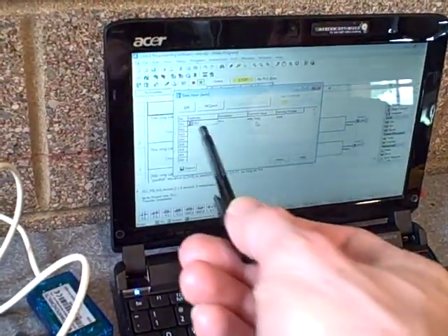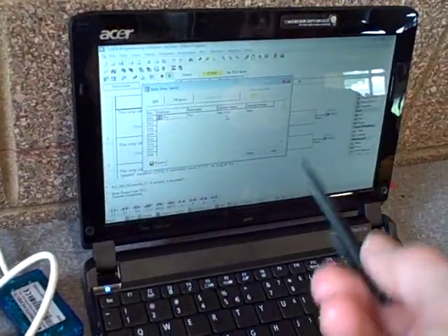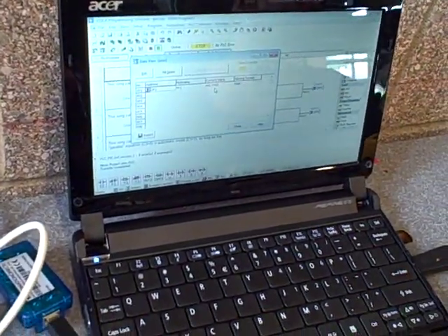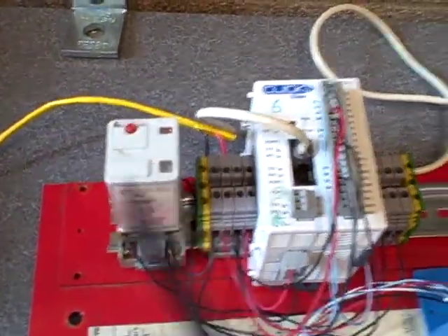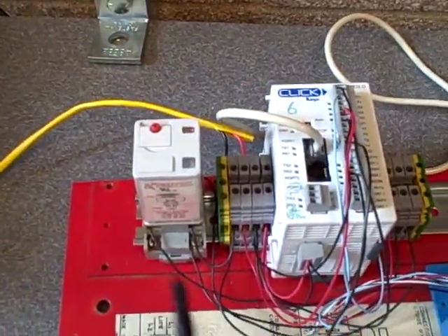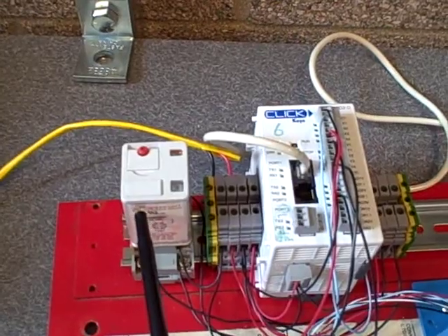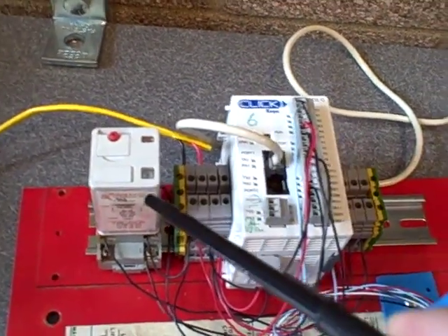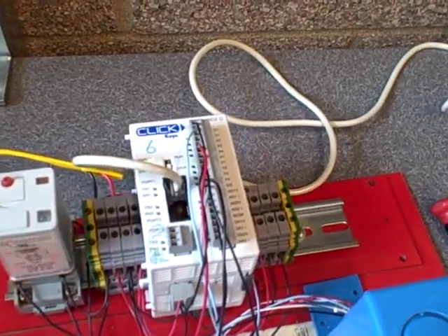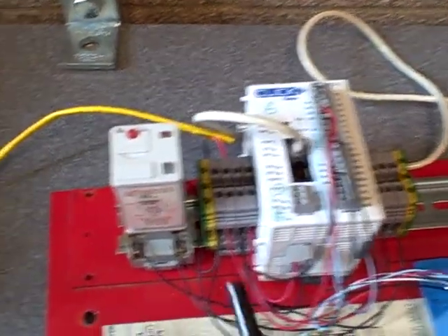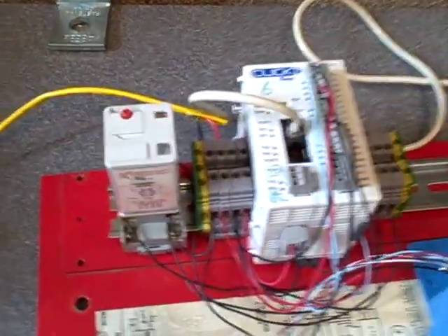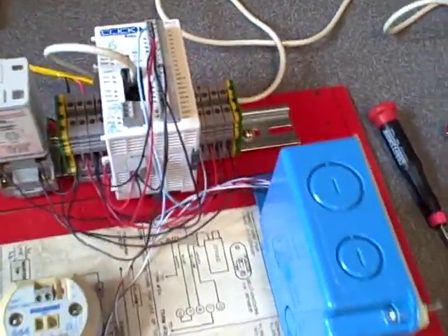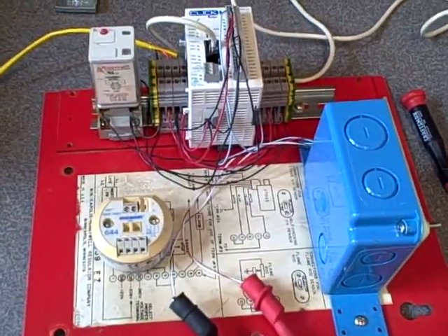So now we can take that DF1 value in the PLC program and write some code that will cause it to activate or to turn this relay either on or off when we hit that point. And what I'm hoping to do is have that relay be something that's energized under typical conditions, so that when we shut down, we de-energize the coil, and that shuts our oven off. That way, the safest failure mode, if that coil burns out, oven shuts down. Perfect. Make sense? Yep. Cool, that's going to be our safety shutdown system on the oven.